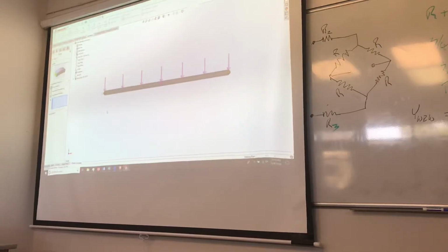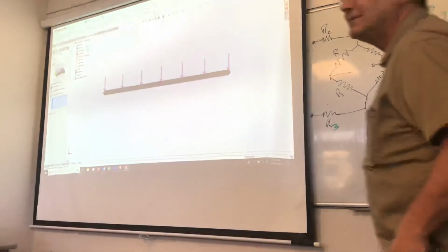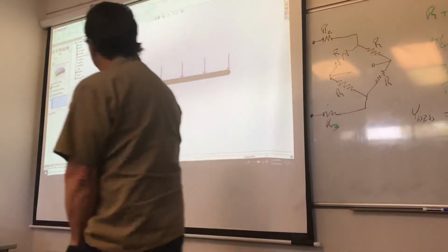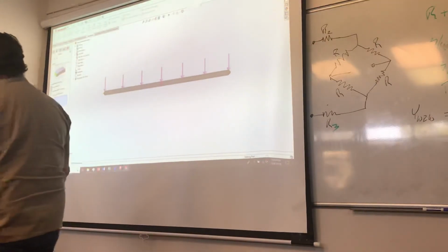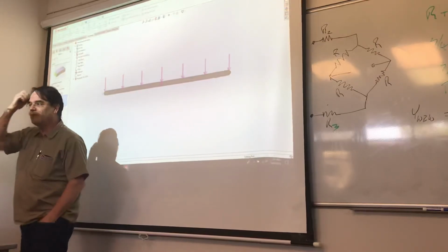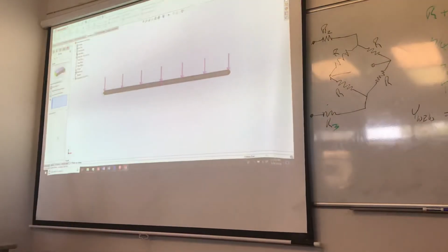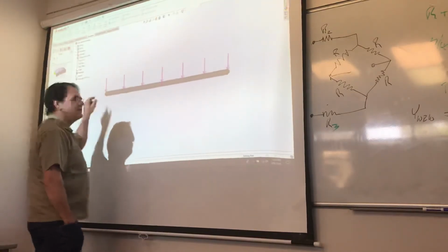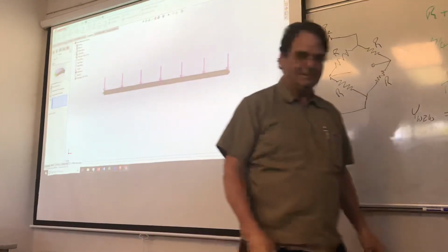It's a cantilever, right? I have 3 points. It requires a joint. I had 3 arrows going towards it. You want to pick fixed geometry. We did, then it's fine. He's got 3 arrows, but you have 1 arrow. No, I got lots of them, they're on the other side. There's one on the top here, and there's one on that one. Yeah, the green one is in the weeds.